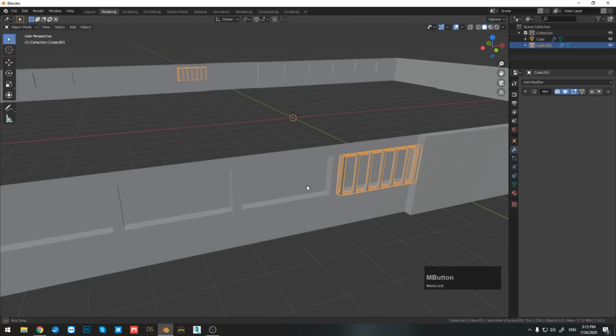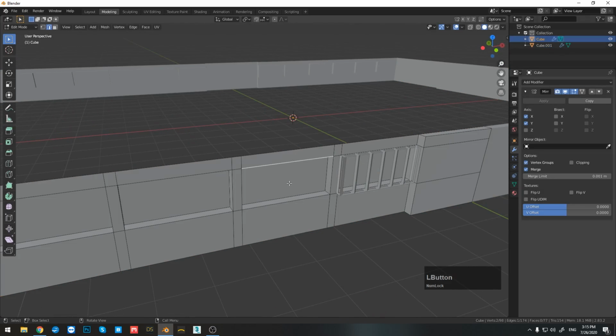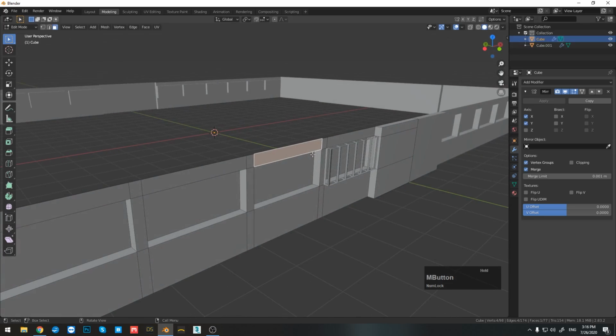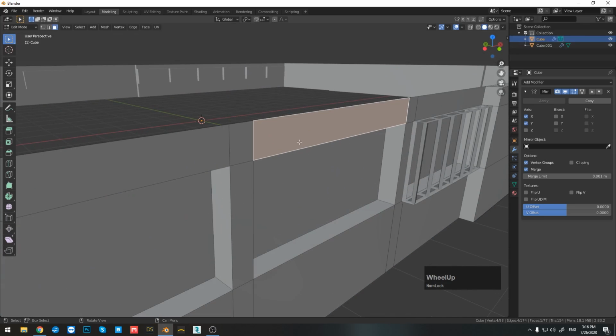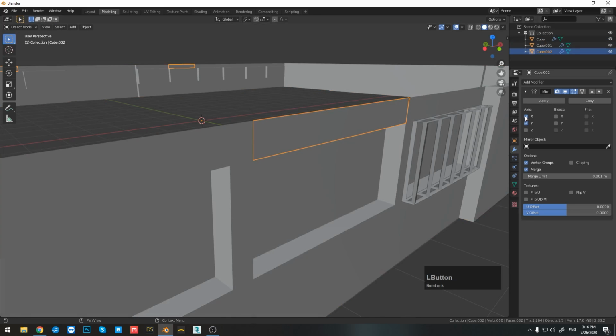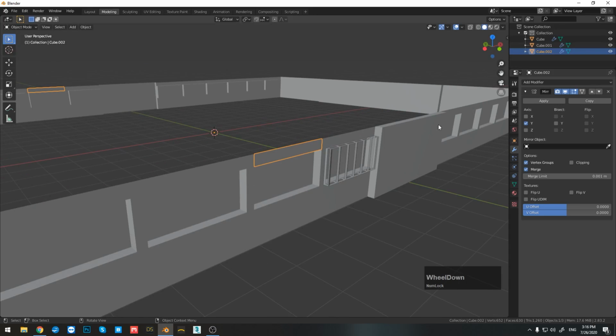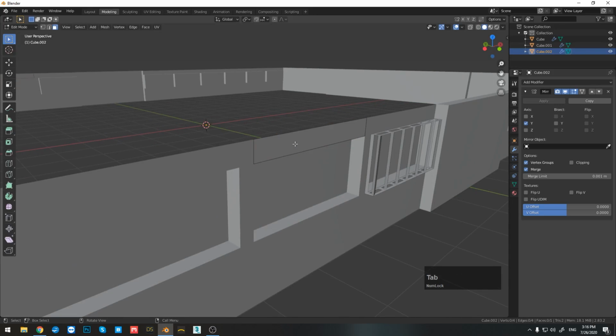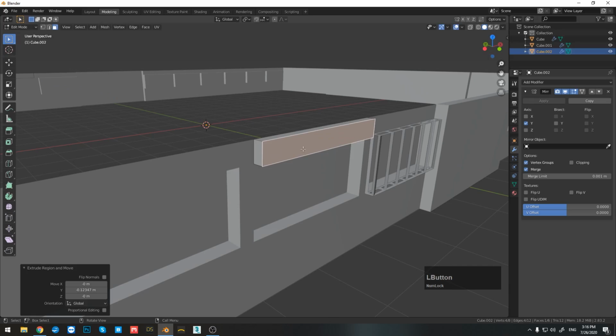Now let's go to the left side, select this face right here by pressing 3 on the keyboard, then press Shift D to duplicate it, and then right click, separate selection. Press Tab again, select this face and disable it on the X-axis so we don't have to see it right here. Then press Tab, 3, then select the face, E and Y to extrude it out.